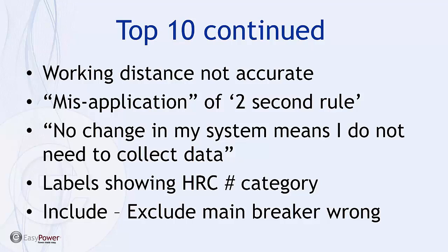Don't be, I think, overly liberal in the application of the 2-second rule. In fact, I don't even like going there. I like looking at each case by case and considering the energy involved. Ensure that you're not shortcutting yourself and your employee safety when it comes time for review, and consider validating the data that has any possibility of changing. Make sure your labels are properly indicating the calorie level.